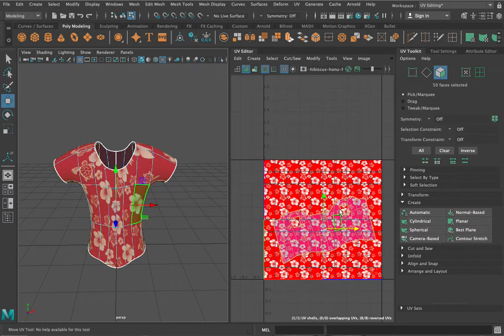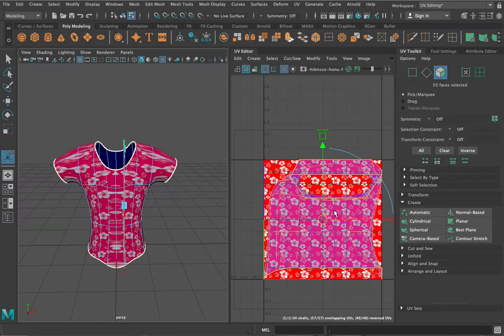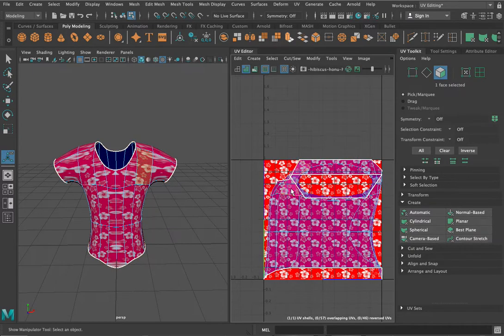Now in the old days, what used to happen is you would select your object over here and do some sort of an unwrap, so you might end up with something like this. Then you would take this mess of polygons, go into vertex mode, and select the individual vertices, and using your W key you would just start to tease these out, right? It'd be like untangling fishing line or something like that.